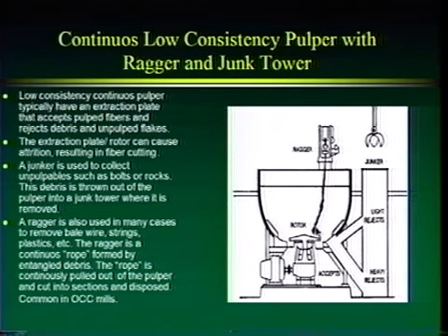It's a never-ending snake. If we continually put wires and plastics into this pulper, then this snake continues to grow. And if we match the growth of this snake with some velocity of removing the rope, then we get a nice, stable, continuous de-ragging process. So it's kind of a unique process, very interesting, and it works. It removes the wires and large plastics.